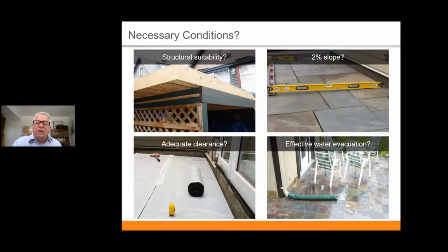How about clearance as far as height from inside to outside elevations? We would really like at least 3 inches and maybe comfortable to 4 to 6 inches is what I hear. I've just read in the National Tile Contractors Association reference manual, from finished elevation inside to finished elevation outside. Why do we need that much drop? To get flashing to work properly.